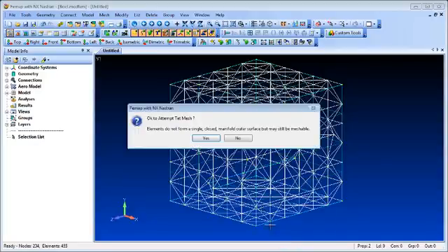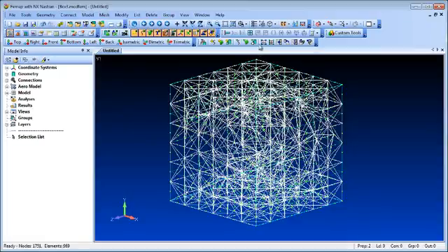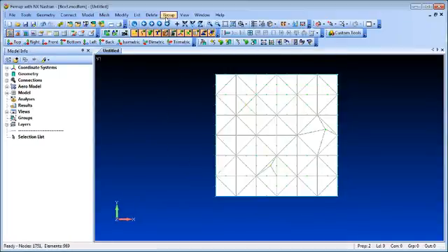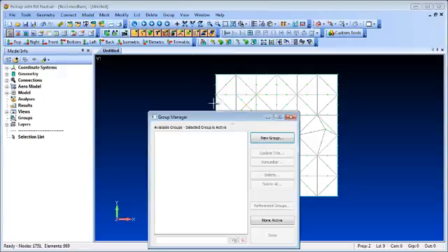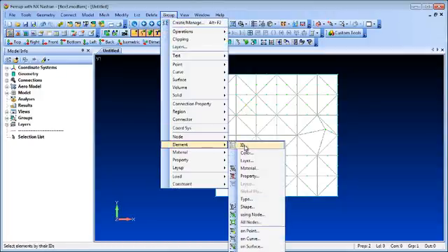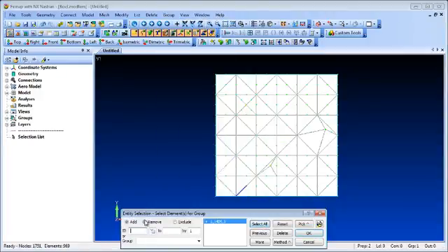Verifying the interior of a solid visually can be challenging, but in Femap we can use the grouping function to create a subset of the model that can be blanked off. In this case, we'll put the corner elements of the block into a group, such that when they're blanked off, one of the interior lines of rod elements will be revealed.